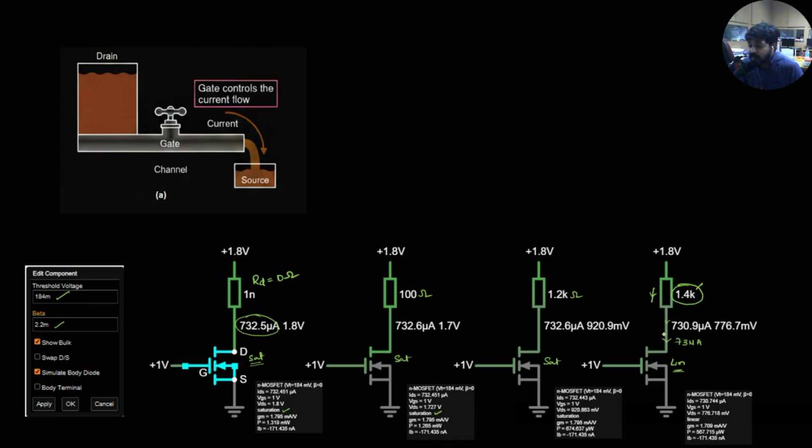When the current is not more than that expected, in that case this electrical node is supplied with less current than is conducted out. Then more charge is going away from that node, so the voltage level at the node will be reduced. This node indicates the VDS of the transistor, and this node indicates the VGS of the transistor.